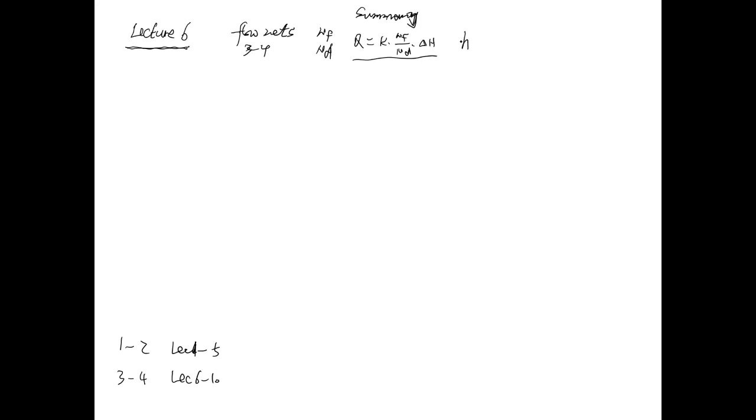You know the total number of head drops, and you know the head difference between the upstream and downstream. You can work out the head drop between each equipotential line, so you can work backward to get the water height of each equipotential line. So that's the water height calculation.